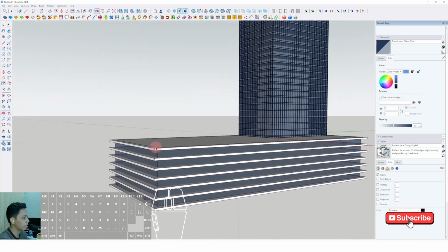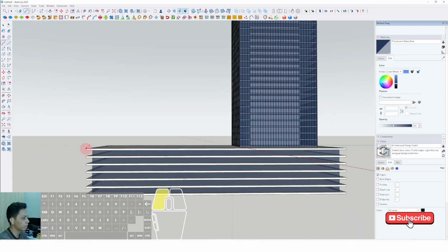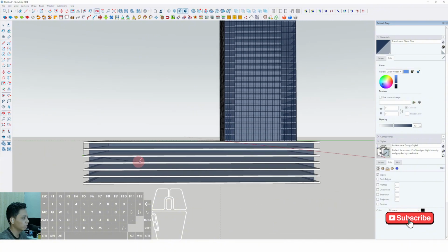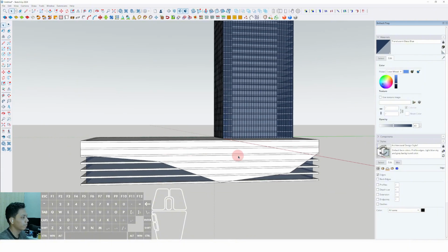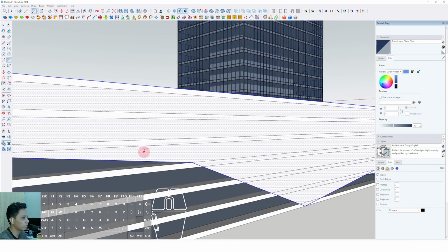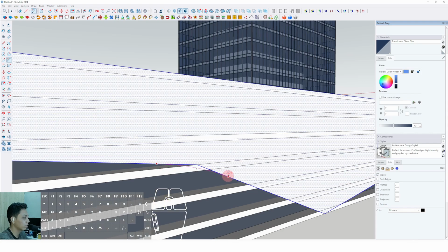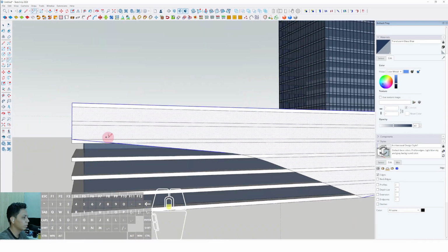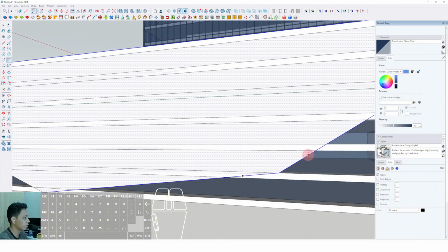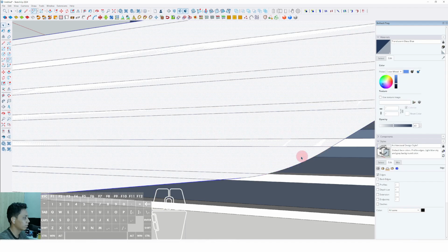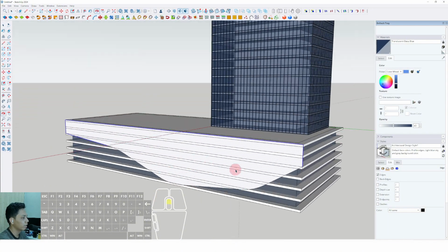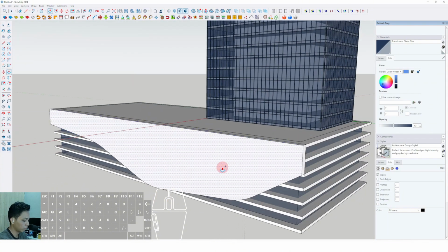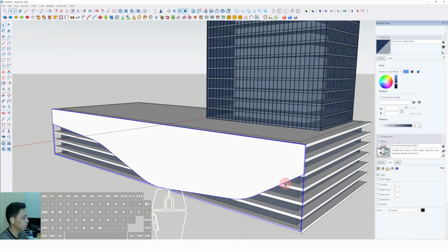And also we can make another design variation using this line, polyline. Okay, we can make this another design concept in here. Then we can also use the 2-point arc, and we can maximize this connection, and also we can push it to the front around 500 millimeters, triple click, right click and make group.